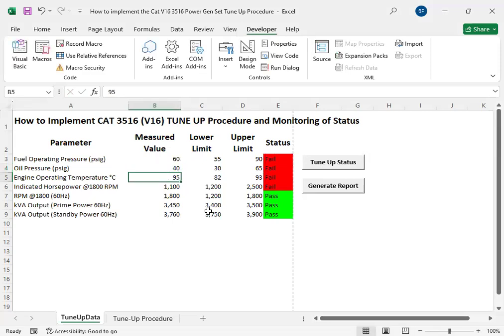And maybe the temperature, because you cleaned the radiator and changed the coolant, maybe you add 50-50 water and ethylene glycol, the coolant should be a 50 percent mixture.